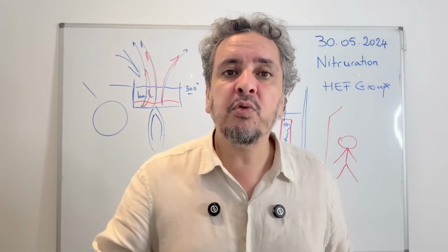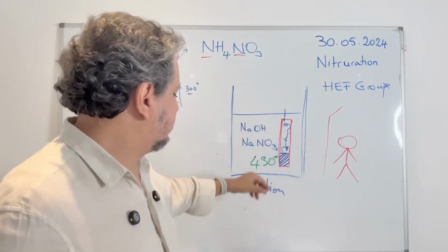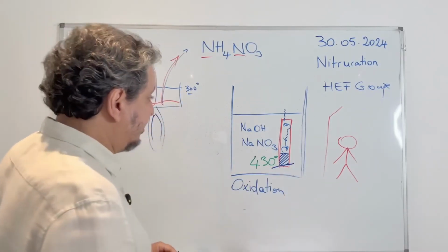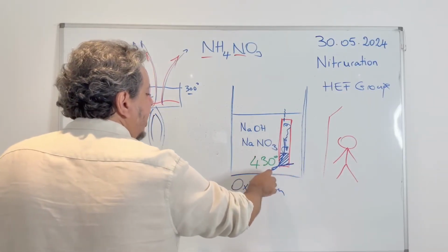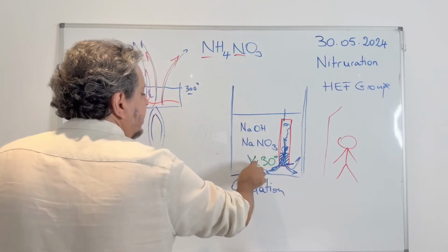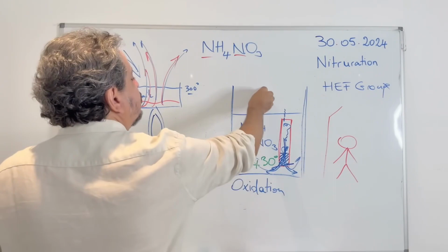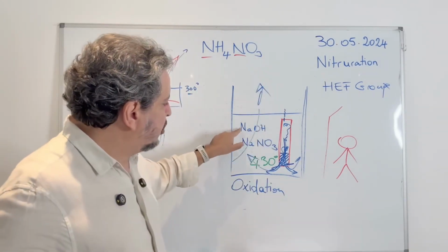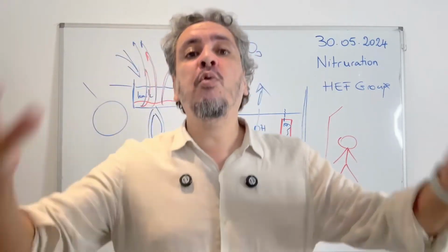He presses a button to start the crane lifting the tubes. The tubes are just starting to lift when the head here is going to blow off under the water pressure. The head is going to blow off and water in the form of steam will get in there, very violently. And what is it going to do? It's going to lift all the contents of this tank. That means 2 tons of NaOH and NaNO3 at 400 degrees are going to be blown into the sky.